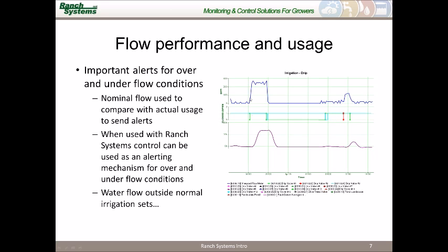And you see here right when the green line opens, about 10 minutes to 2 hours later, it reaches its maximum flow rate. So it's got a very low fill rate for this particular block. And then what we've also done concurrently with this is that we've created a model for the customer so that they can see exactly what is going on with the system in proportion to what they'd expect. So we know by working with users that they have a certain expectation of their irrigation system. And so this is a very good example of a performance curve.